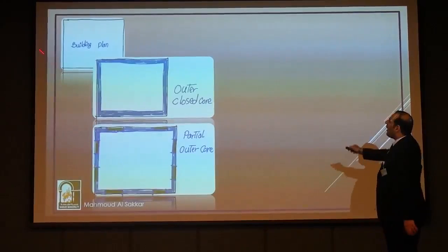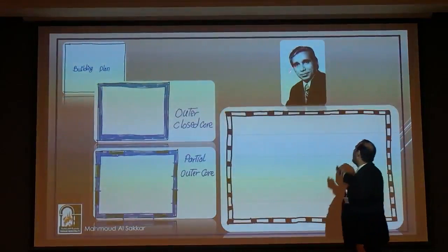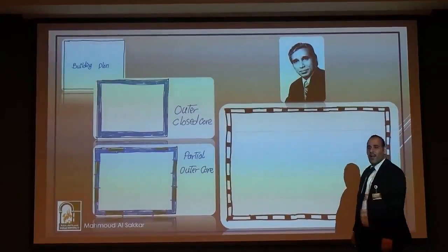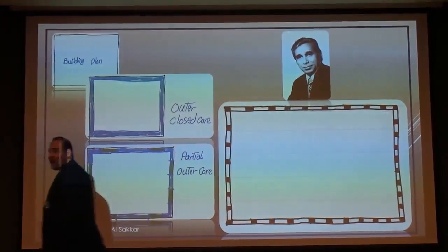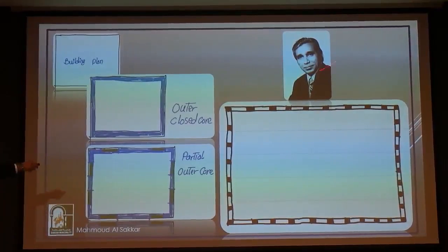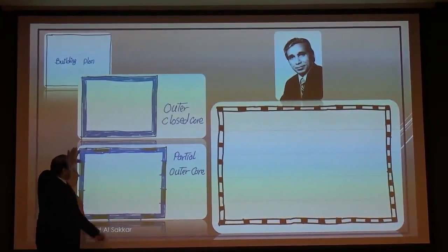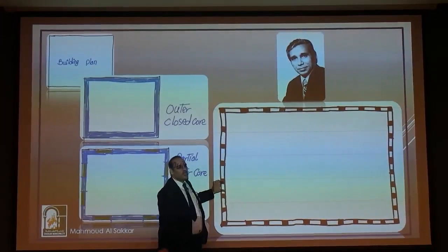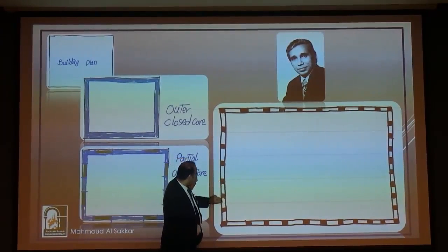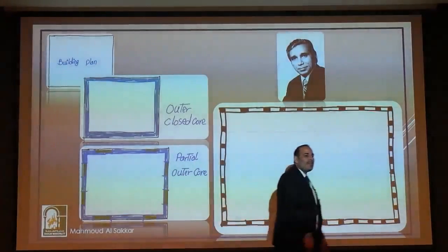Now I have come up with a building where I have to make an outer core and push out the core. But that guy, Fazlur Rahman Khan, a very honorable man, I like him so much, he's from Bangladesh, a Muslim guy, he promised another system. Instead of making a partial outer core, I'm going to make columns spaced only 1 meter or 2 meters, maximum 1.4 meters. Every column. He made it like a hull, an external hull.